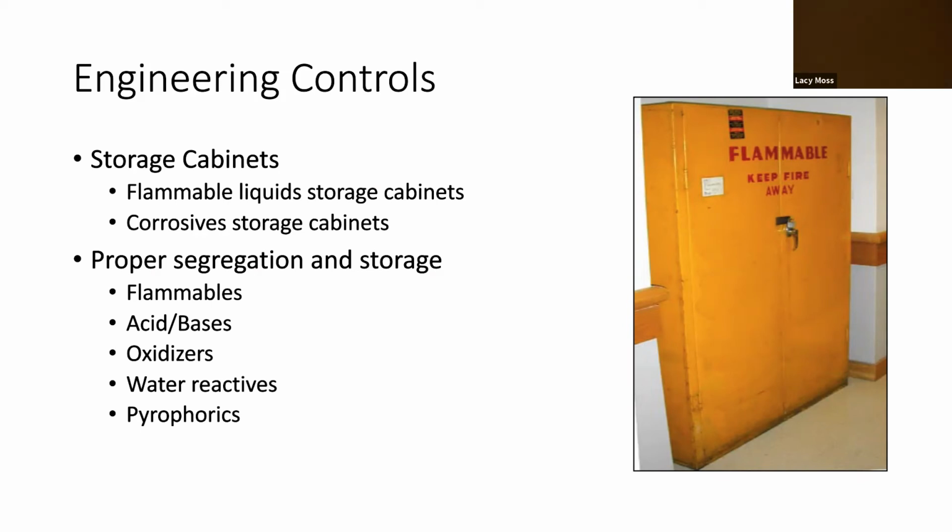Then you have corrosive storage cabinets. You want to make sure chemicals of different classes are segregated. So acids are separated from bases. Oxidizers are kept separate. Water reactive reagents are kept away from water. And pyrophorics are also treated appropriately.